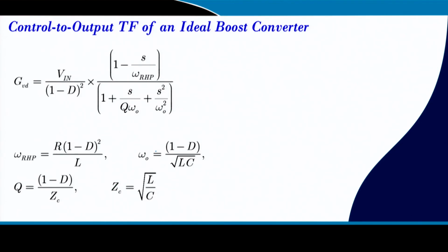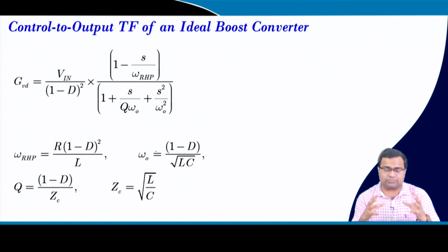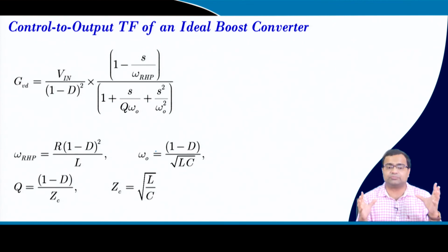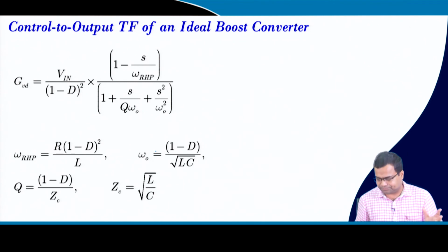So, we will say more in detail because we will design voltage mode control of the boost converter, and we will show all this case study there, how to design the compensator so that we can get the maximum performance using voltage mode or current mode control in a subsequent lecture. But one thing I can say is that I have shown you the response due to the small signal model and the response due to the actual switch simulation, and they are closely matching.